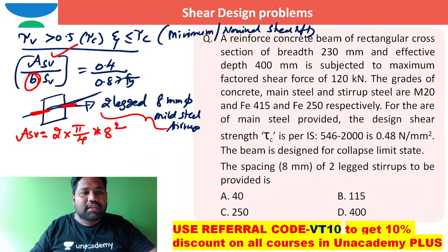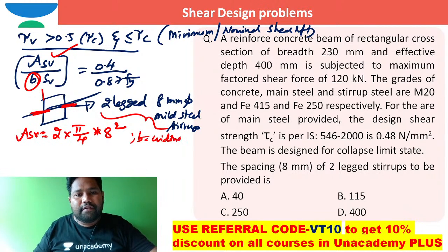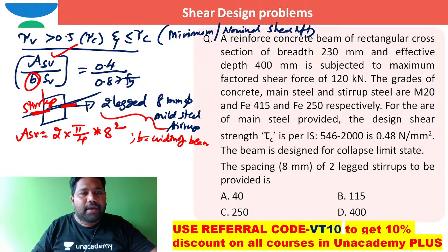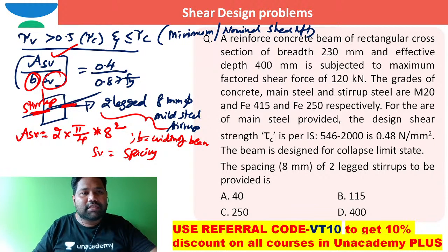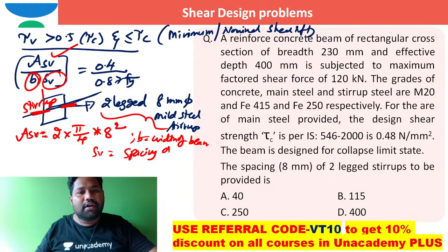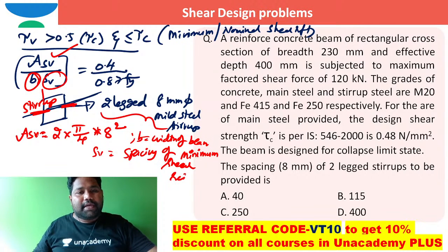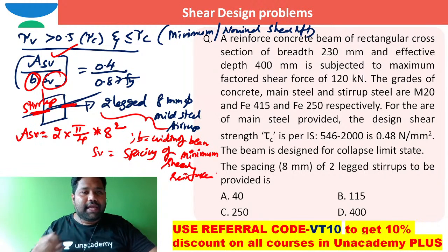b stands for the width of the section. This is the stirrup. Right. Sv stands for the spacing of shear reinforcement, which is the spacing in the above formula. Spacing of minimum shear reinforcement, I can say.